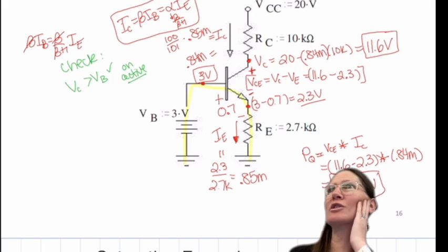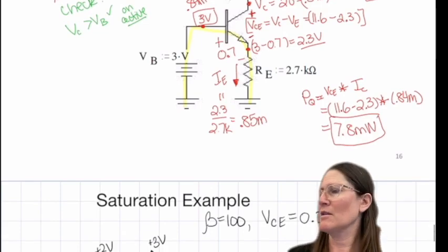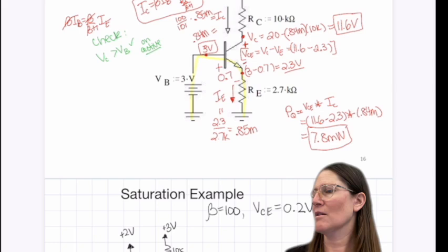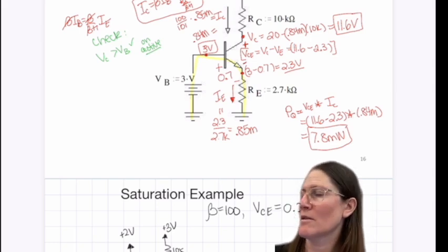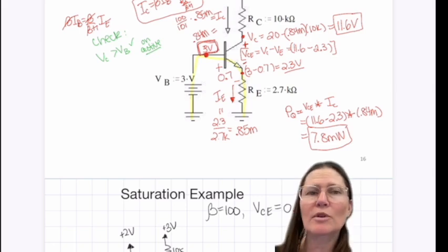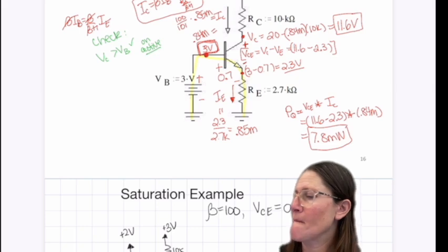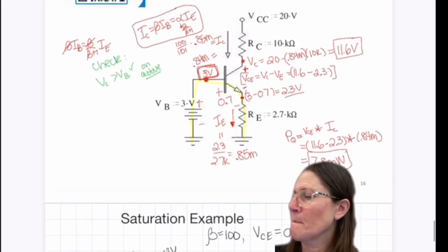All right, other questions? Yes. So is it the VB that's the voltage going into the lower branch on the other side, like the yellow line? Is this VB right here? Yeah. But you found the voltage right after that one diode, and you did 3 minus 0.7. So how come for the top diode you can do the 20 volts minus 3 volts over the resistance? So here to here would be VCB.